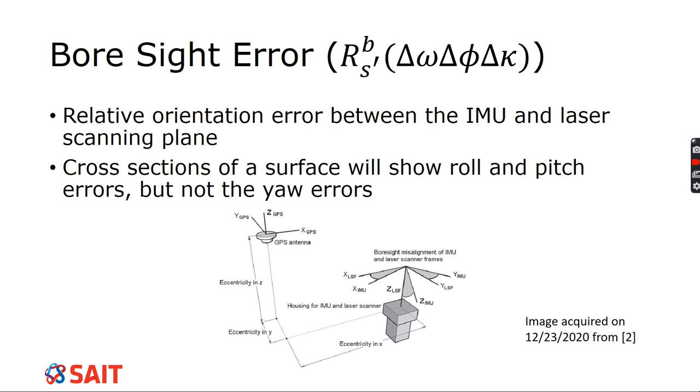So everything could be placed correctly, but when the bore sight is supposed to be pointing straight down, perhaps it's out by 3 seconds, right? If you project that 3-second angle over 600 meters, that adds to a larger and larger error every time.